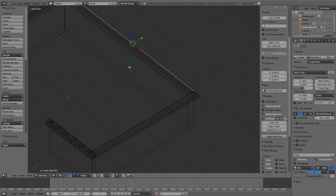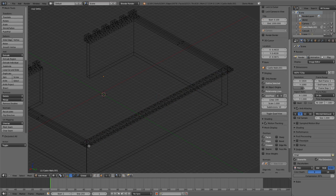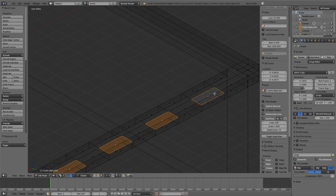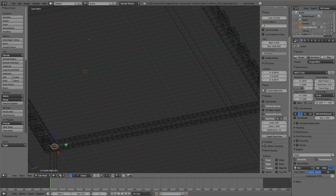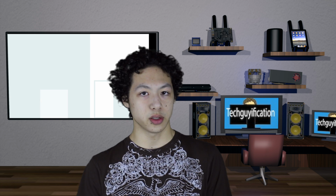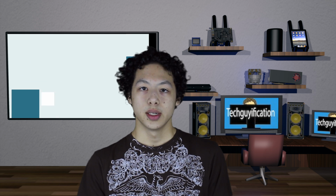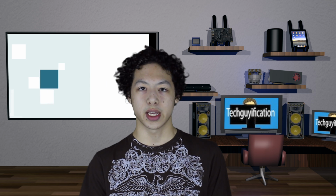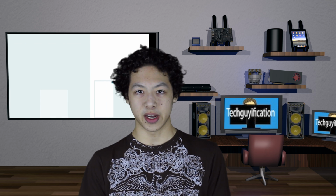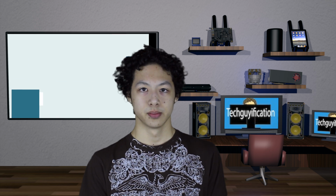So now do the same thing on the back side of the castle, except this time you'll need to click the subdivide button 4 times as opposed to 3. The upper right hand block may be a bit larger than the others, but that won't be an issue, so don't worry about it. Next, do the same thing for the left and right side of the castle, and you'll need to subdivide that side 4 times.